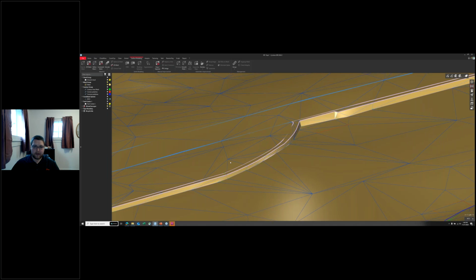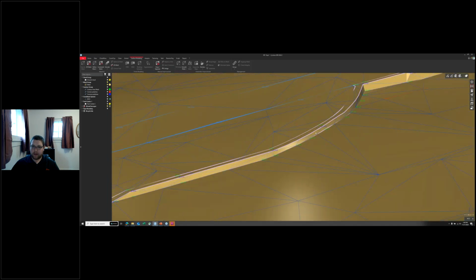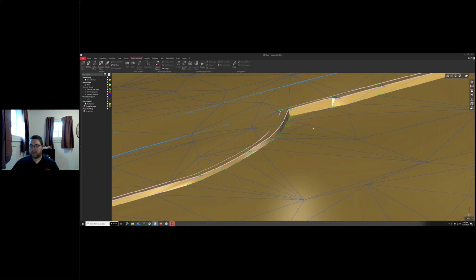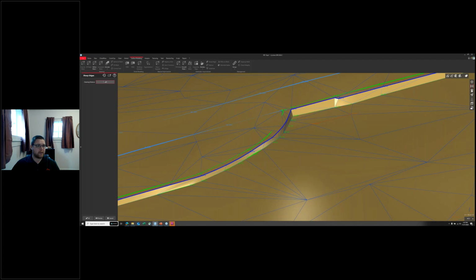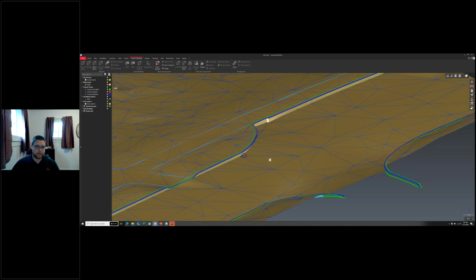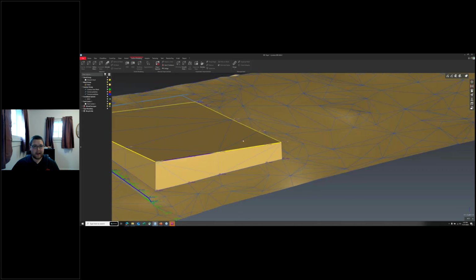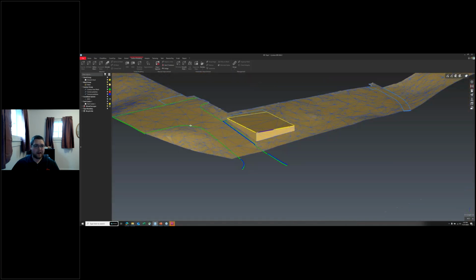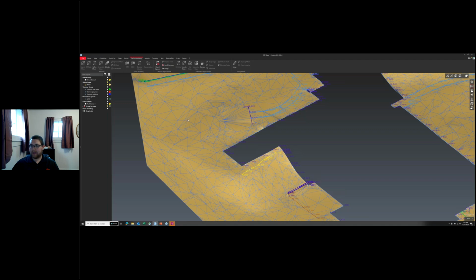What I should have done is selected that whole curb here. And you can see it's holding all the face of curb points because there's that big vertical drop. But I could do it this way, sharp edges, and if there's anything that's been removed, I could just get it added back in real fast here again. And now it's holding my vertices on my back of curb for me. So we have that. Over here, it's still holding this nice platform, concrete pad that we did. No worries there. Everything else, it's ready to go really for AutoCAD.